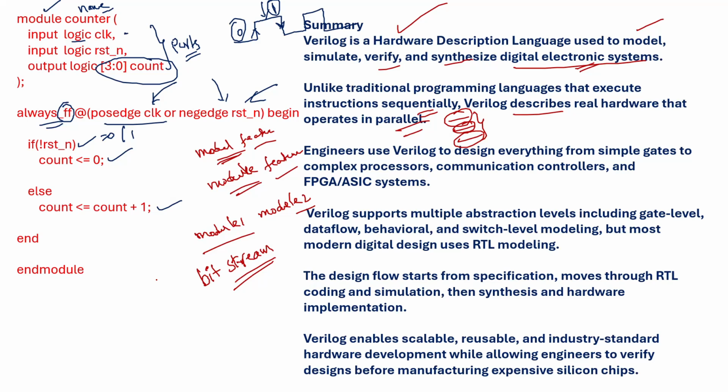So simply consider MIPI. You know about MIPI and its architecture. In the application layer you write one module. Pixel to byte is one module you will write, and then a low level protocol is one module you want to implement, and then protocol lane management is one module you need to implement, and the file layer is one module. All these are related to the transmitter side. For the transmitter side you need to design another module, and for the receiver side you need to design another module. So just in a simple circuit, almost 7 or 8 modules are there, right?